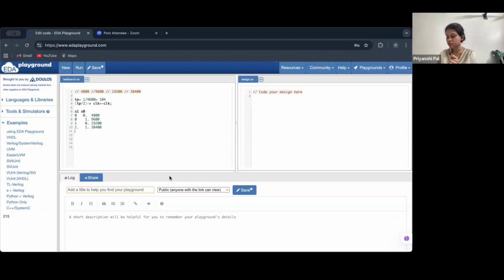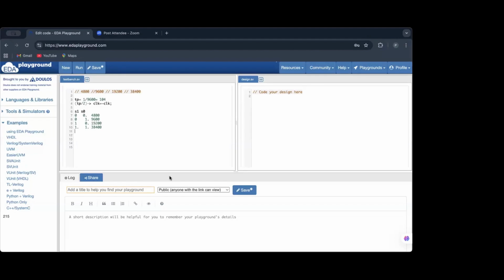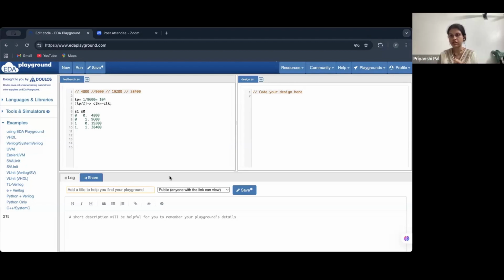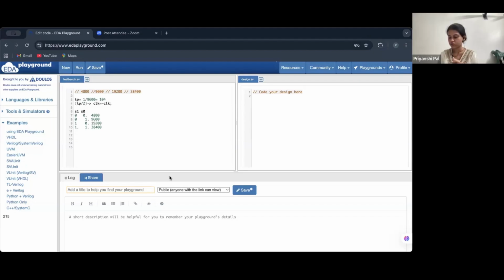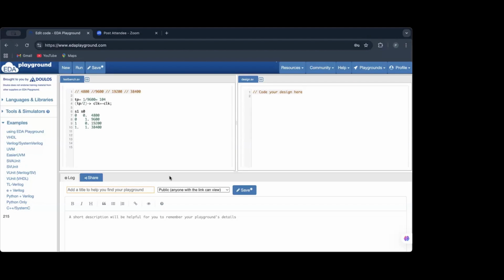And I think if both masters send the request to the slave at the same time, they won't get an acknowledgement from the slave. But one will win, and we will not have corrupted data. One master will get the acknowledgement and the other won't get any. Yes, any one of them.